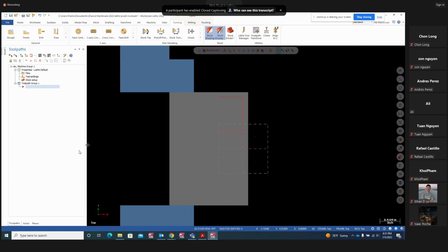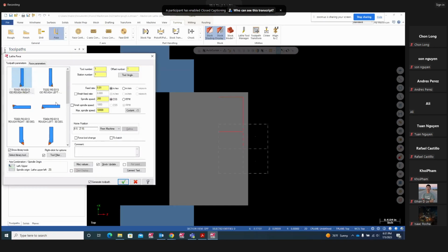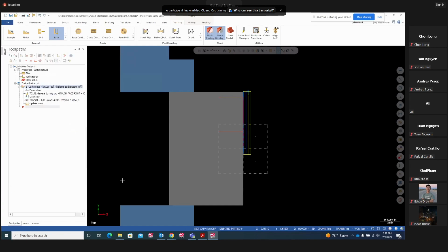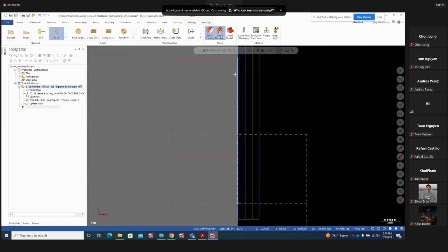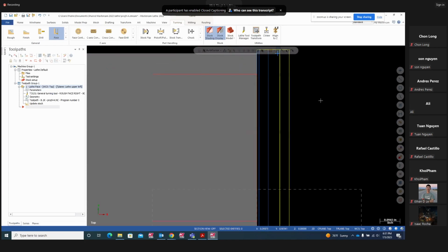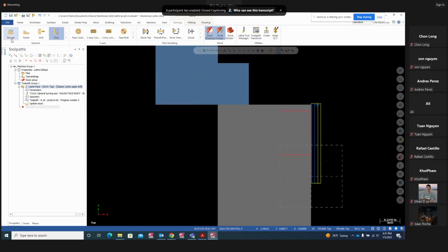Okay, rough face, pick up our facing tool, which is going to be my 80 degrees, and we can use rough step over 0.050,000, and rest everything is same, guys. I'm going to just skip those, just going to face it, and then if it's finished, it pretty looks like it's finished the face. Yeah, that's good. So now I'm going to go ahead and OD rough.